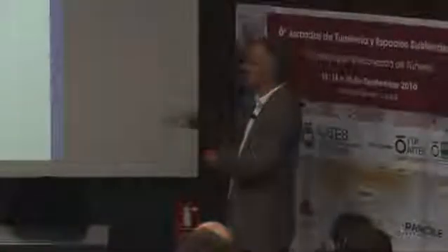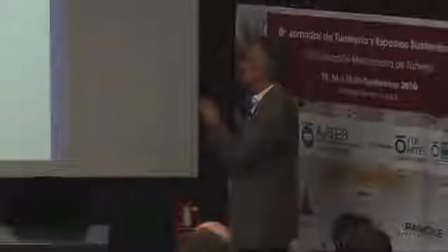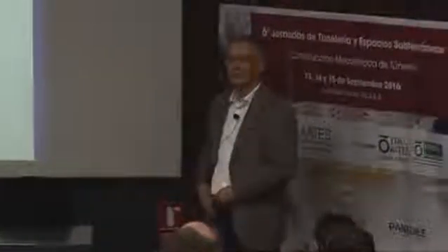Here's just an example to visualize what happens when the face support pressure is too low. You see how nice and local the settlement develops slowly from the simulated TBM, and how it just goes straight up. Of course, this is in beautiful cohesionless sand. You have different conditions on most of your projects, but the effects are more or less the same.